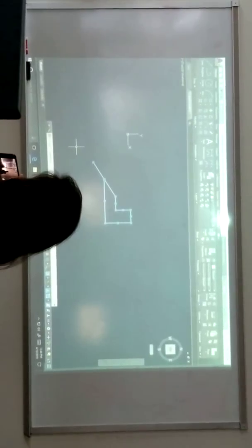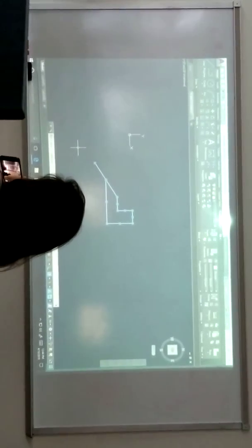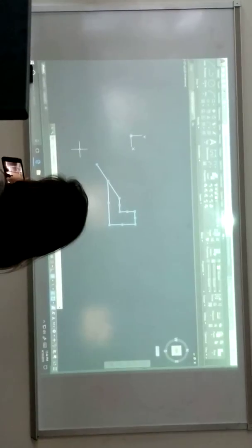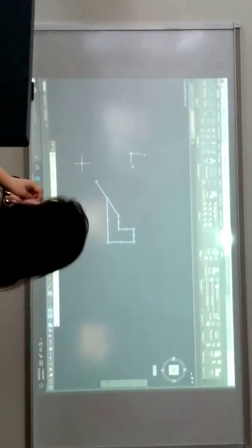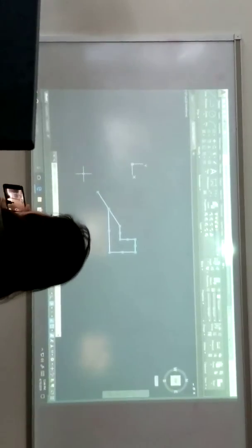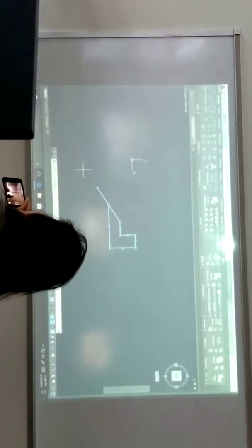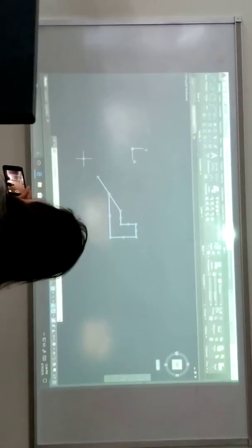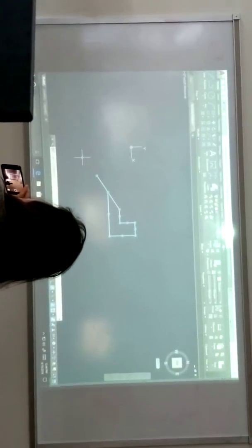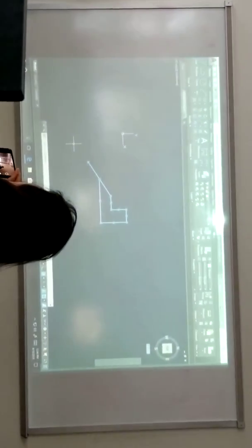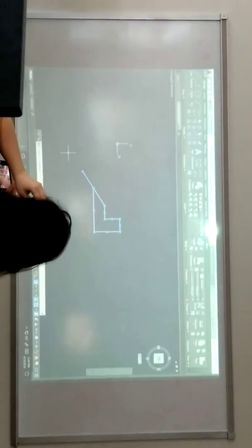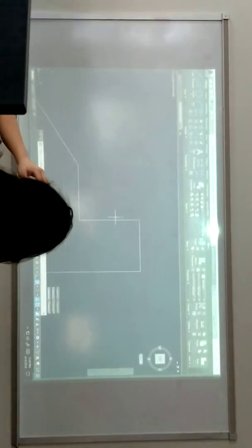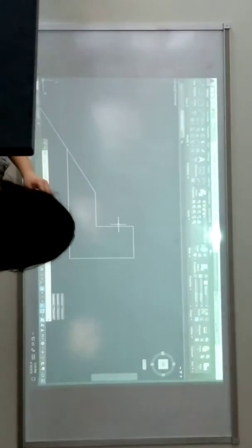AutoCAD can do line weight manipulation. How's AutoCAD do line weight manipulation? Based off of what? Color. Colors. Okay? AutoCAD says if it's blue, I'll let you set up a plot style to say everything that's blue, print with 0.0001 millimeter thickness. Okay? If it's red, it'd be 0.002 millimeter thickness. If it's cyan or whatever, and you can change those in your plot style. Right? But the thing is, I can't see that the way it'll print. It's a translation. It'll translate something that's red here.